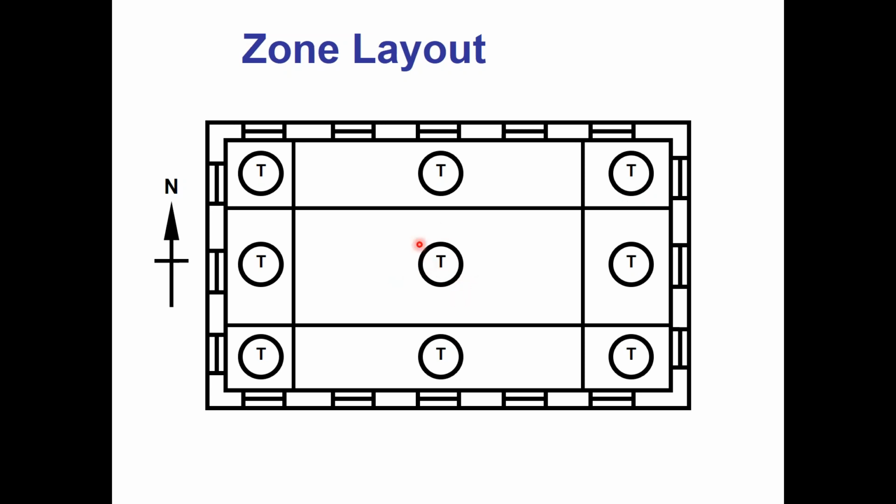For that reason, you need to keep the interior zones separate from perimeters. So I don't want to have this be one big zone with the south and the interior sharing one VAV box and one thermostat. That would be bad news. Generally speaking, each perimeter needs its own control. The interior needs its own control. And then if you're doing a really good job, the corners will get their own control, because there's sometimes going to be a west zone and sometimes going to be a south zone depending on where the sun is, right? And then the same with all the other corners.